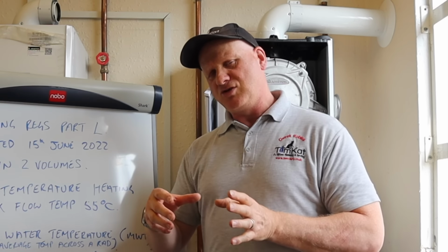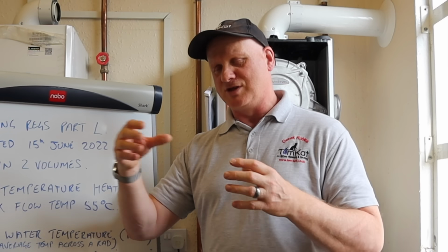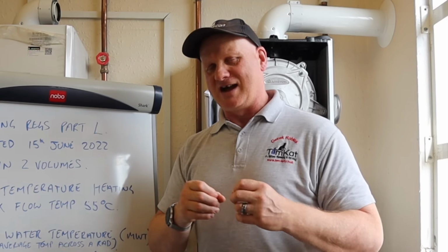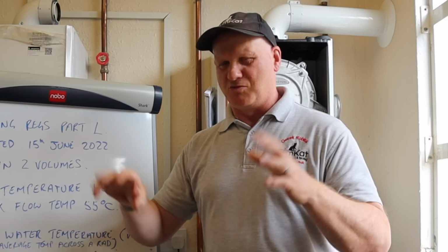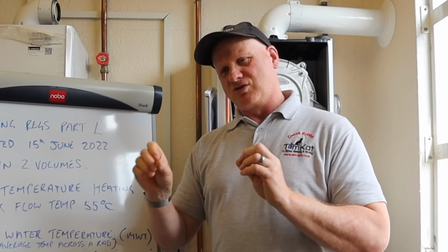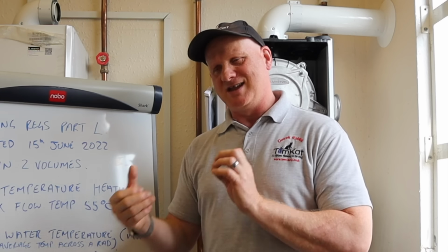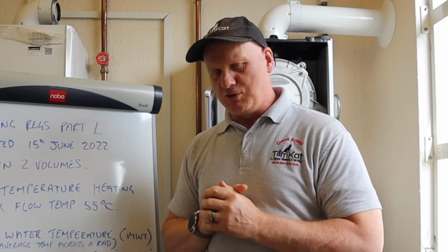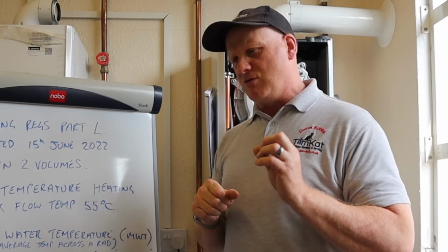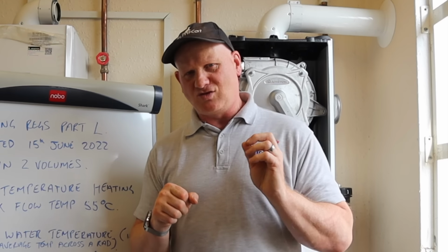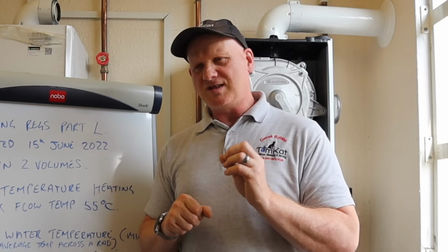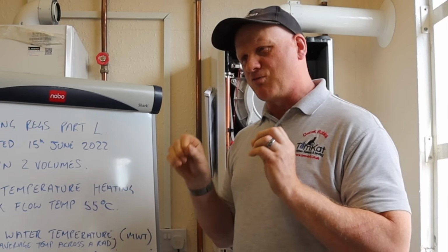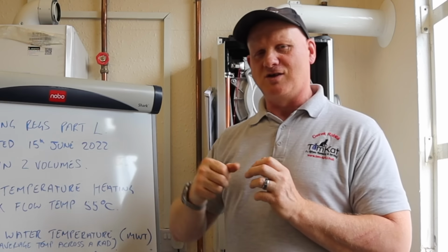But the lower temperature compared to the higher temperature with the longer time run, actually you will save more gas doing that than you would do setting your boiler onto maximum and running for a couple of hours, because your boiler wants to try and keep running all the time and stay in condensing mode and be able to save and use that latent flue heat. Hopefully, now you've listened to a bit of science towards it, you now understand why lowering your flow temperature is important, but you can't just rack up to your boiler and go and turn it all the way down.